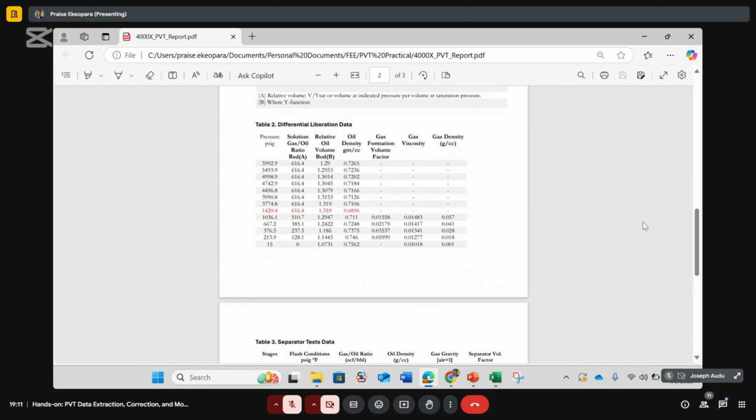As a good petroleum engineer, when you see those plots, your eyes should go to your already known standard trends of Rs, Bo, Bg, and compressibility. If anything goes outside those, you can then query what is happening there.